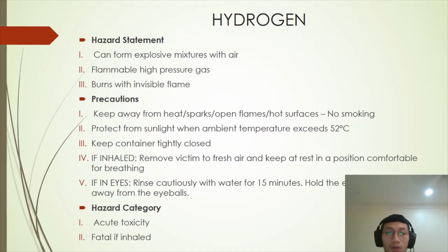Okay, we always have to wear protective gloves, protective clothing, eye protection, face protection, and respiratory protection when handling hydrogen. Okay, if inhaled, we have to remove victim to fresh air and keep at rest in a comfortable position for breathing. If breathing still is bad, we have to contact the physician.